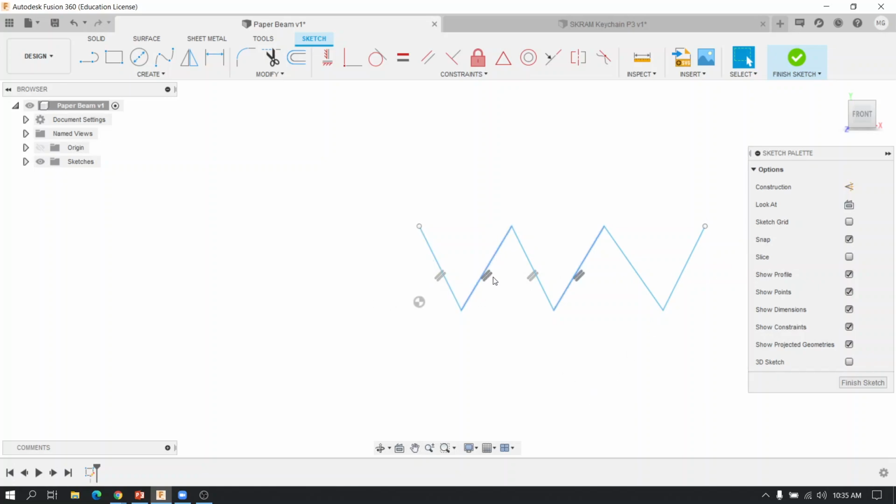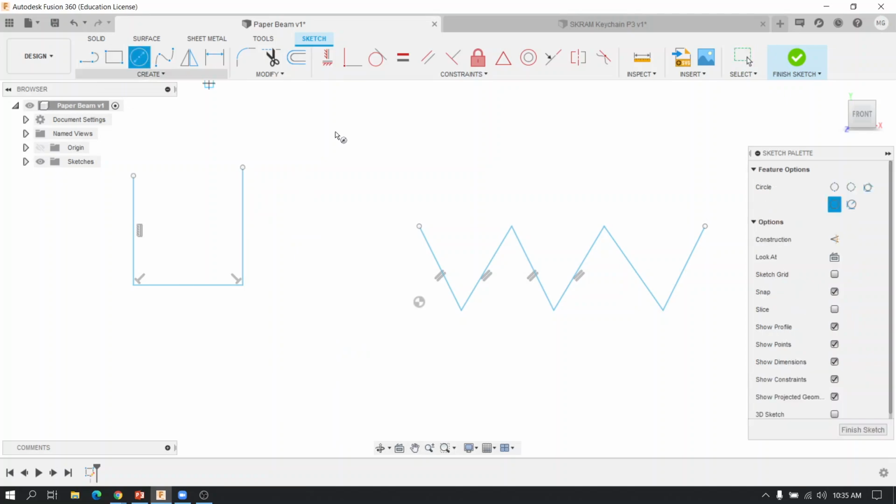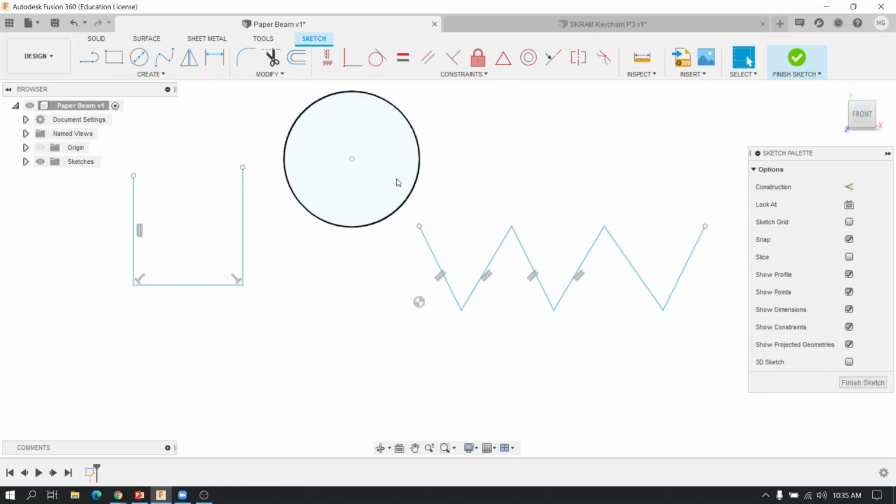I'm going to extrude this line. It has no solid, so it's just going to extrude an infinitely thin line in a moment here. And then I'm going to give it thickness when I'm done. So very easy. So if you were to fold this into a box, don't do this, but if you were to have folded it into a box, then you would just literally do that. Okay, if you were to have folded it into a cylinder, then you could probably just do a circle, and so on and so forth. So whatever your shape was, just create lines to represent the edges.